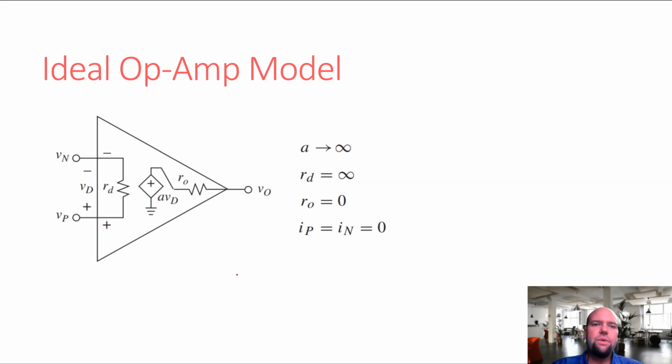And so the actual gain of op-amps: some op-amps have very high gain. The classic OP77 op-amp typically has a gain of over 1 million. But an LM741, you're typically talking more like 60,000 to 100,000 or so. So it's different. And some op-amps, especially high-speed op-amps, sometimes the gain will be less than 1,000 for those types.